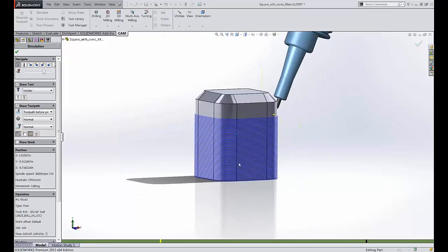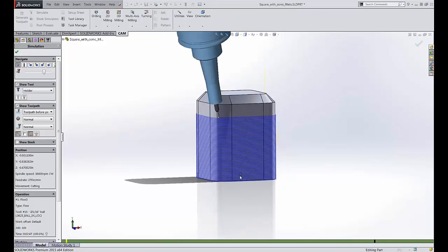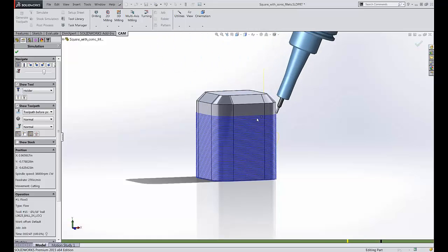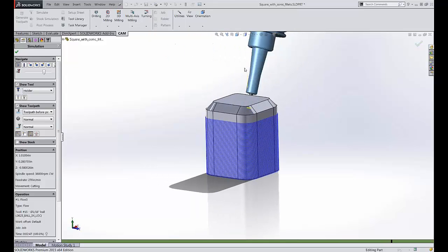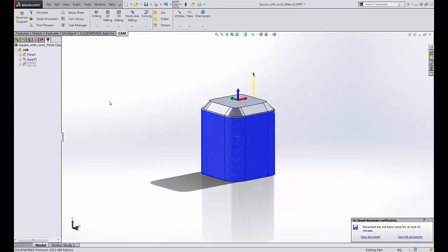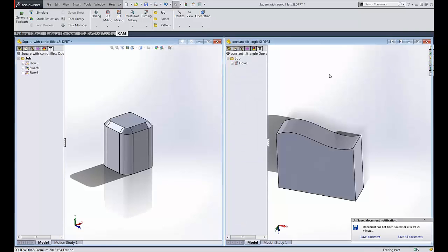But like that's pretty neat. You get a toolpath that's able to cover this whole entire surface here with a tool that's 3 times diameter. I think that's a 1/16 end mill cutting about 3 inches deep. And it could go infinitely deep as long as you don't run the tool holder or the spindle into it. But like I said, that's not a great example for showing simultaneous 5-axis stuff.